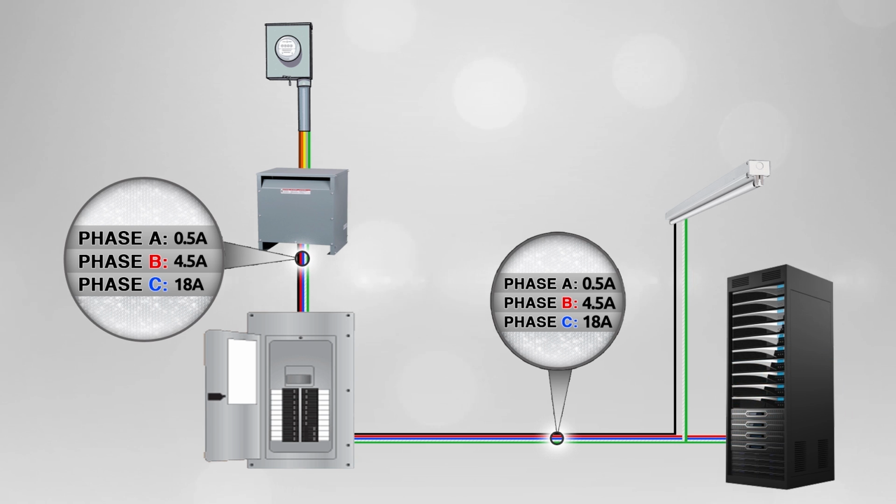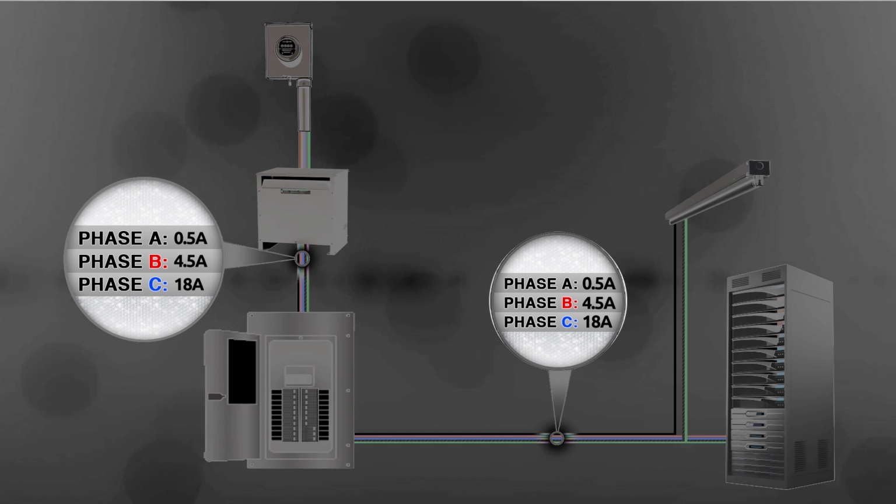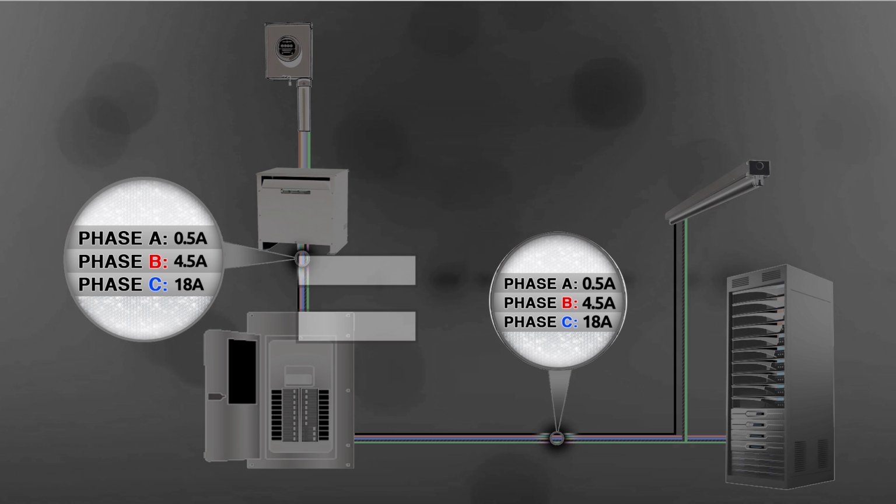Also depicted here are the ground and neutral wires. We have exaggerated the load imbalance in order to demonstrate the effectiveness of the automatic phase balancing feature of 3DFS technology. In a typical data center, the imbalance is not as substantial as this, but is always present due to the nonlinear nature of server rack power consumption. Please note that the power drawn on each phase from the transformer is identical to the demand on each phase.